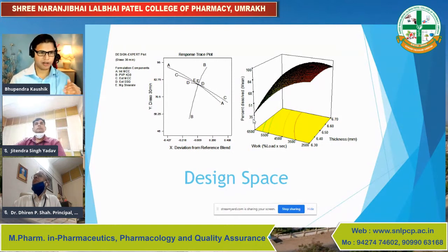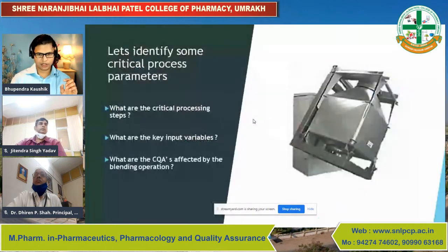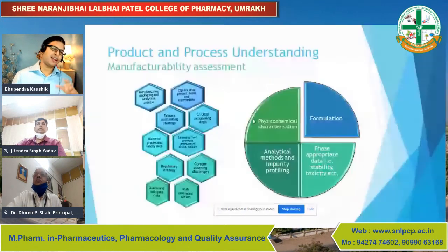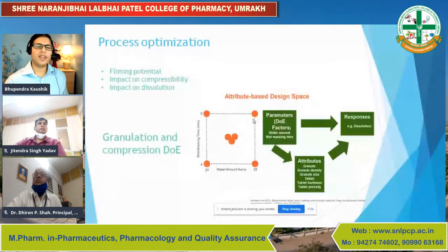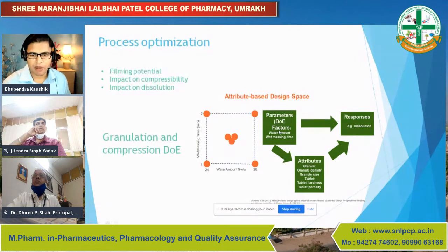I'm repeating myself, but this is very important to know, because in order to generate useful data, it's important that you pick the right variables and the right measuring response. I'm going to go to another slide which will give you more idea about it. This is linked to that process. On this slide we are looking at the response, dissolution, as I mentioned. What we are monitoring and measuring is attributes, which are granule density and size, as I mentioned in the IPO diagram. What we are playing with, or stretching, is the water amount and wet massing time.